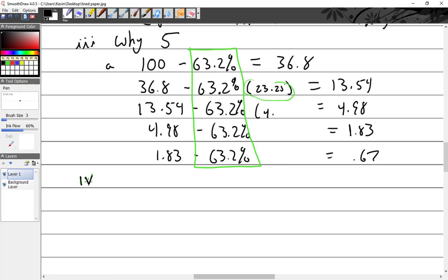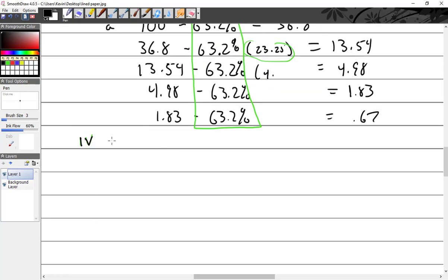Okay, how many time constants does it take to charge up a coil? How many time constants to discharge it? 5. Okay, that's based on 63.2%. You're probably not going to need to remember that. You're not going to have to work this, but I just told you why, because somebody would have said, well, why 5 time constants? And I told you why. But I didn't tell you how long the time was.